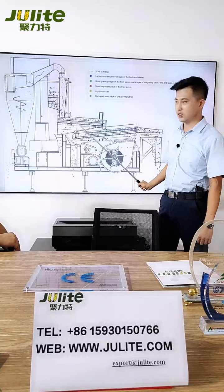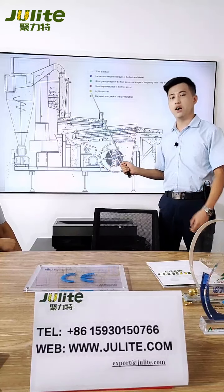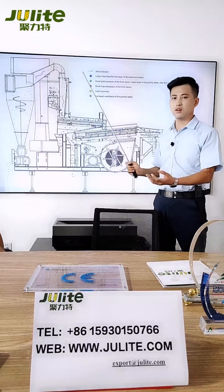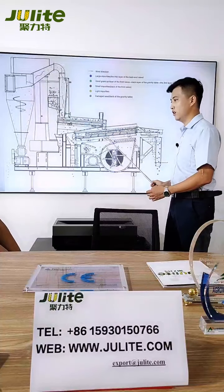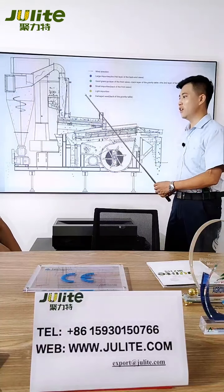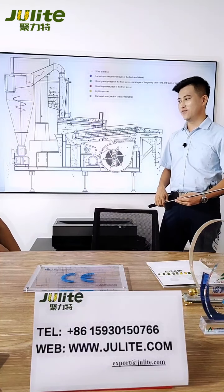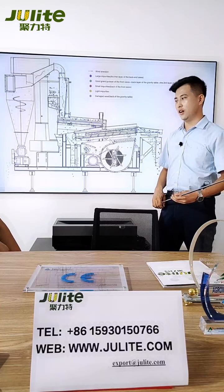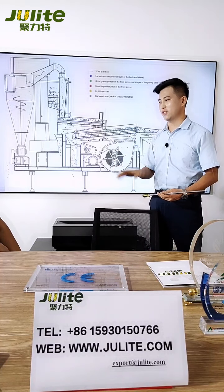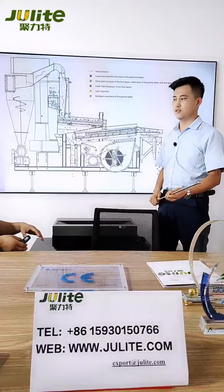This is the second point, and the front sieves are to remove the smaller impurities, like the smaller size. Because if too much of the smaller size goes into the gravity tables, the table's whole size may be the same as the smaller impurities. Then what problem will happen? We will go with the materials. I think so. In that situation the gravity table may be blocked. Yeah, maybe blocked, and it will affect the final results.